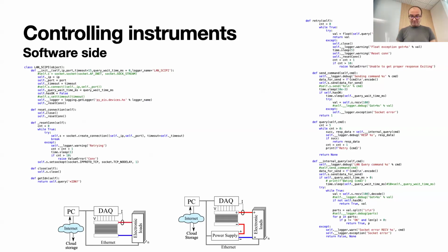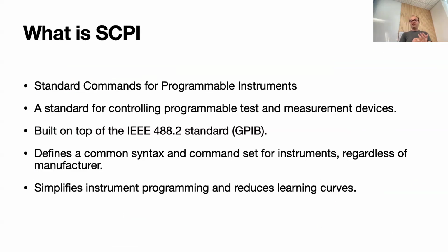For every instrument that I'm using, I have Python code that can control it. But as here we are not using Python, you can do it really simple in LabVIEW, and the guys here have already done it with their instruments. The protocol is really, really simple. It is a text-based protocol, and it defines a syntax that is common regardless of the instrument, regardless of the manufacturer. So once you get a hold of how this works, you can use it to control almost all smart instrumentation wherever you are.